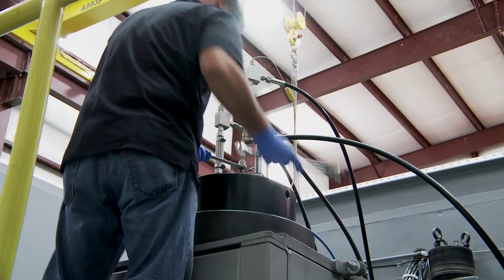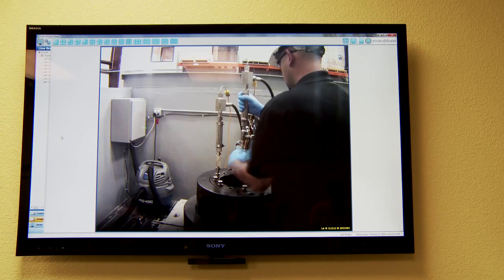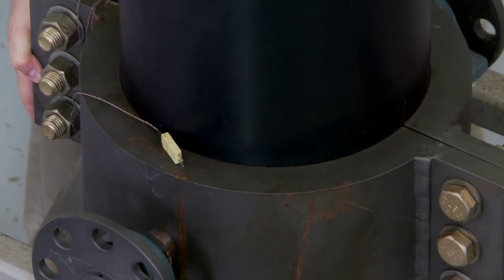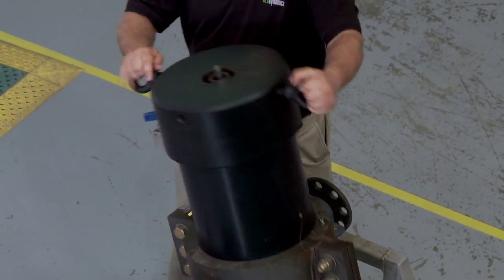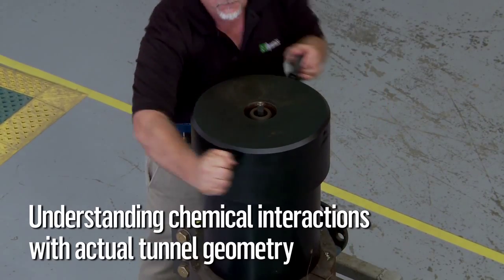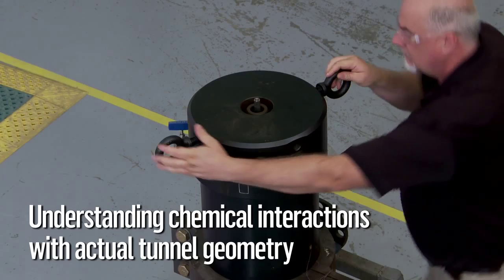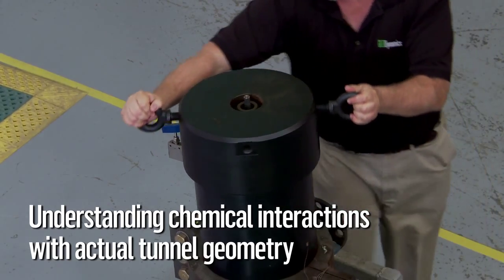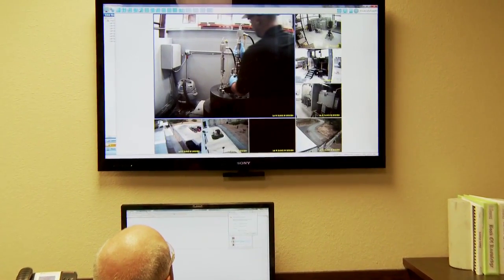The treatment cell allows us to take an already perforated core and place it at stress and pressure and temperature conditions that might exist in the downhole well, and then treat that perforation tunnel and the surrounding rock with any chemical that we want, so that we understand the chemical interaction with the real geometry of the perforation tunnel instead of just an artificial representation of that tunnel.